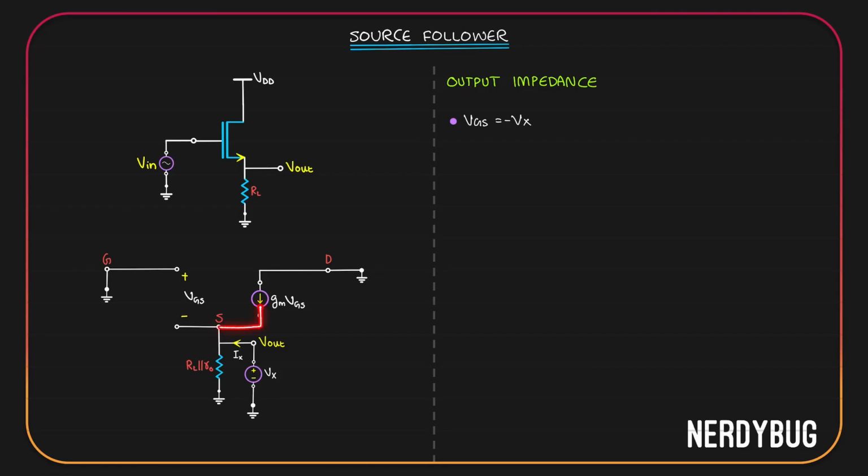gm VGS is coming into the node. Ix is also coming into the node. There will be one more current flowing through RL parallel to R0. What will that be? RL parallel to R0 has a potential Vx across it, so that current is going to be, according to Ohm's law, Vx divided by RL parallel to R0. So we can write gm VGS plus Ix is equal to Vx divided by RL parallel to R0.